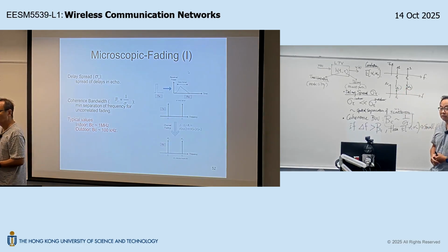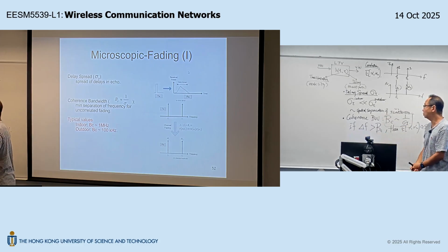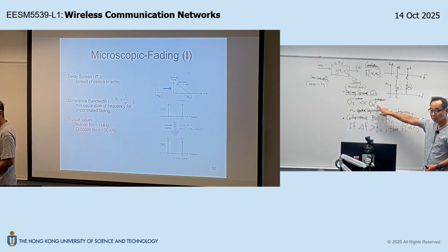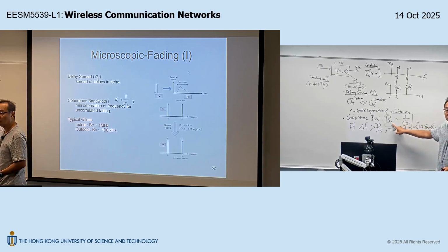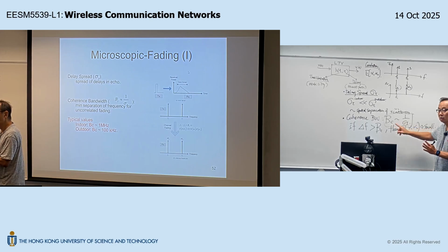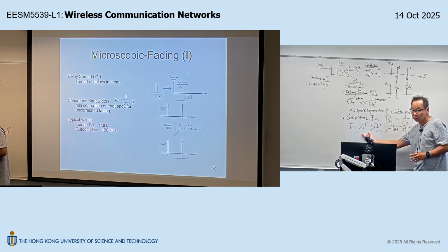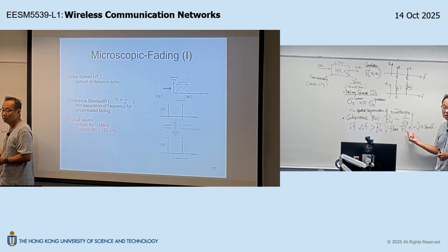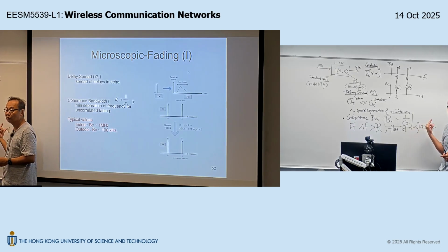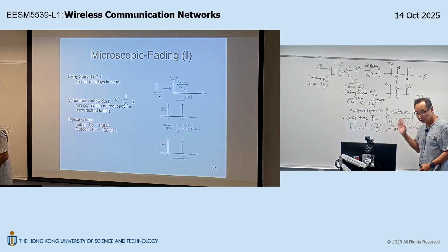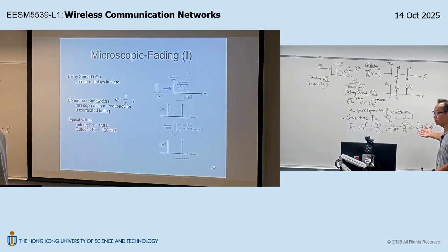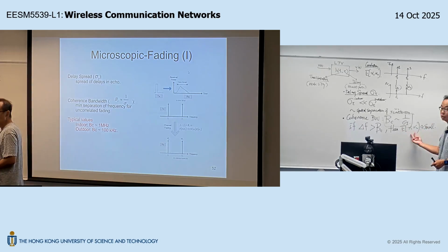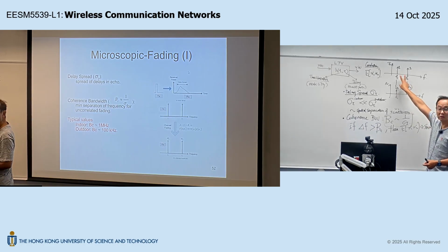Okay? On the other hand, for outdoor propagation, delay spread is larger. So that means the coherence bandwidth for outdoor would be smaller, right? So that means in an outdoor situation, the frequency separation doesn't need to be that large, and I can still see the fading response being uncorrelated. Is that okay? So this is just a neutral statement. At this point, I didn't say anything about good or bad about uncorrelated fading. I'm just describing a phenomena. The phenomena is the correlation of this fading response will be less and less correlated as the frequency separation increases.